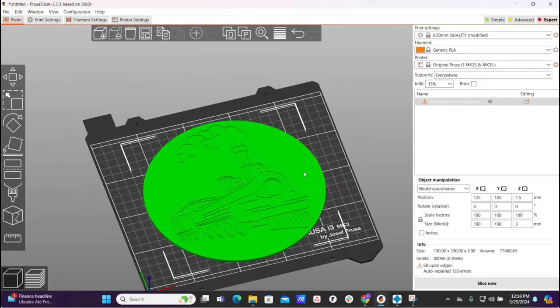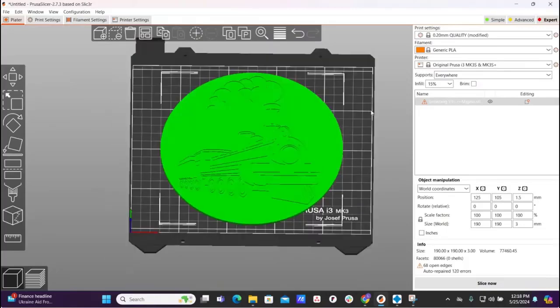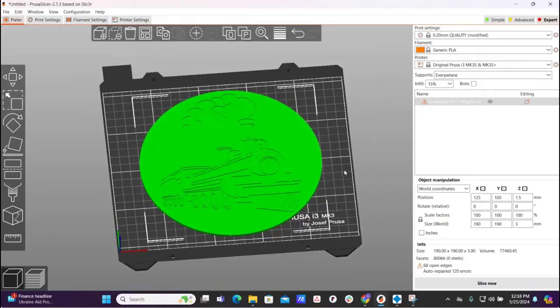And then we looked at it as a two-tone thing. So you could even, if the layers stack on top of each other, make multiple color prints by setting a color change in the slicer software. So let's quickly go over our settings that we talked about earlier. I have 0.2 millimeter layer height, which is a pretty typical layer height that works just generically for everything.